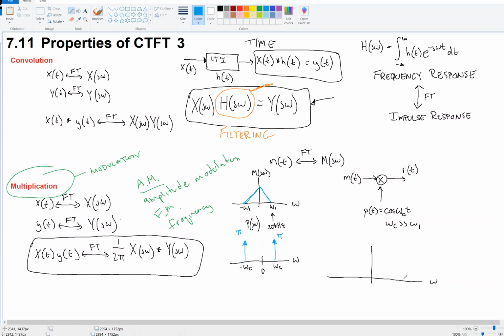So what does that do? It shifts by omega c. Right? Convolving anything with a shifted impulse gives you a shifted original signal. And because of the pi, or 1 over 2 pi, and here's a pi, this makes 1/2. And then for this impulse, when I convolve it with the triangle, I get a shifted impulse down here, right, at minus omega c, and its amplitude is 1/2.